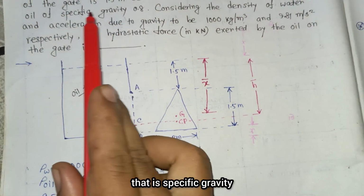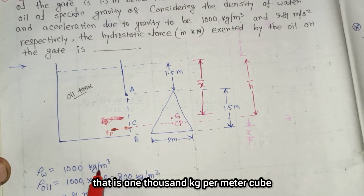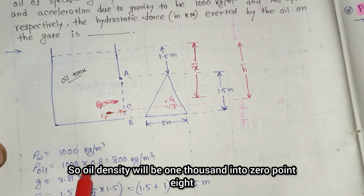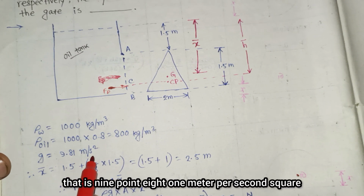The density of the oil, that is specific gravity, is given, that is 0.8. So what is the density? The density of water, which is given in this question, is 1000 kg per meter cube. Oil density, since specific gravity is given, will be 1000 into 0.8, that is equal to 800 kg per meter cube. g is the gravitational acceleration given in this question, that is 9.81 meter per second square.